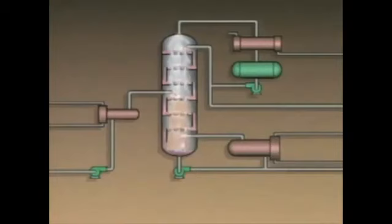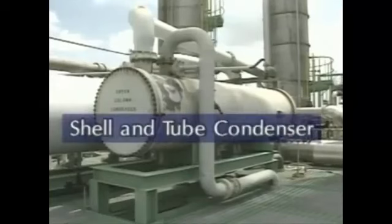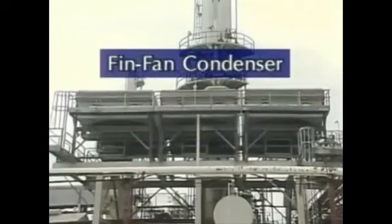For example, heavier uncondensed vapor could rise up the column, mix with the overhead vapor, and be carried into the overhead condenser. In a distillation system, a condenser removes heat from the overhead vapor and turns the vapor back into a liquid. 2 common types of condensers are water-cooled shell and tube condensers and air-cooled or fin fan condensers. Both types of condensers can experience problems. Many condenser problems are related to the cooling medium that flows through the condenser. These types of problems can ultimately affect the amount of cooling provided by the reflux.